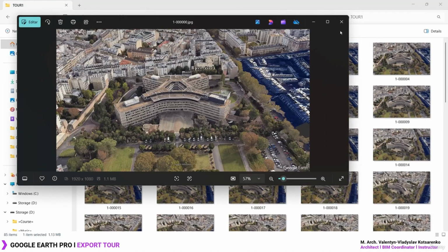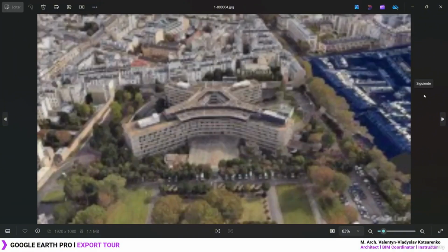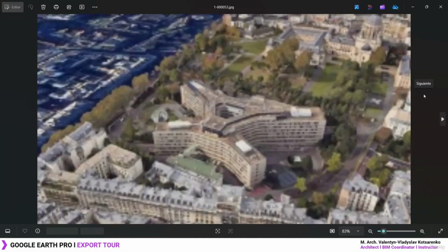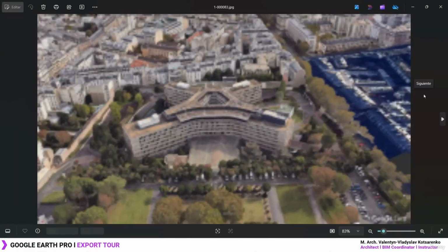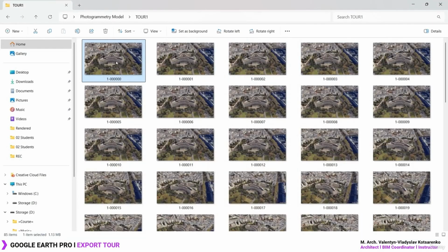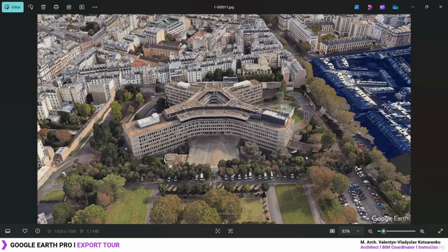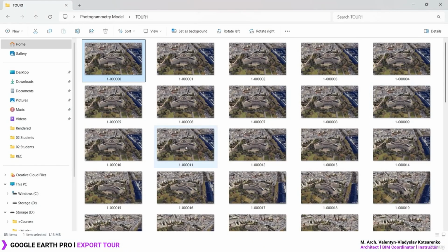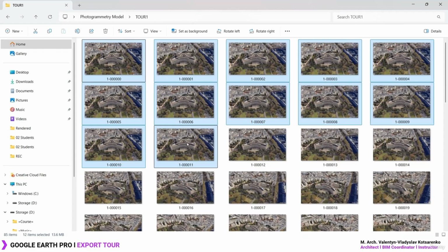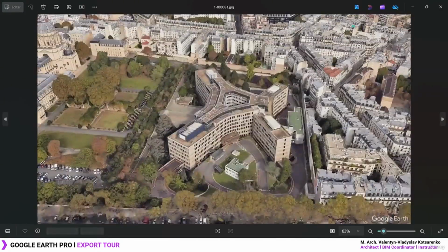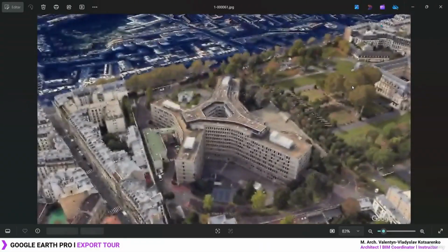What we want to do is create a bunch of images, a series of images, something like this, which will create the basic orbitation move for the building, okay? Now make sure that if you notice right in the very beginning, it's going to lag a little bit. So maybe we can delete the image number from 11 to the previous images, because it's pretty much the same. So I'm just going to take image number 11, then select with Shift image number 0 and delete them. Okay, so we got only unique images generating the orbit movement.